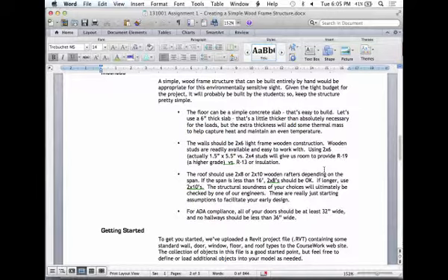Okay. On top of that, we're going to put some light frame wooden walls, and those are what we call stud walls. In terms of what's going on with those walls, we'll have layers to them. The middle structural layer will be the 2x4s or 2x6s. For this structure, I'd recommend 2x6 lumber, because that'll give us room to put R19 insulation. Really insulate it very, very well. Now, just so you know, 2x6s really aren't 2x6, they're really 1.5 by 5.5. The 2x4s are really 1.5 by 3.5, more or less. So there's a nominal size as well as the actual size.